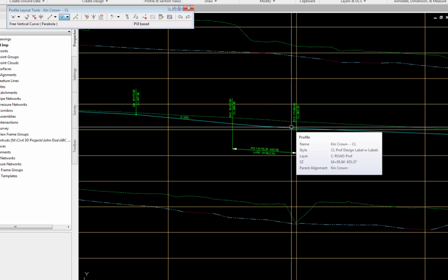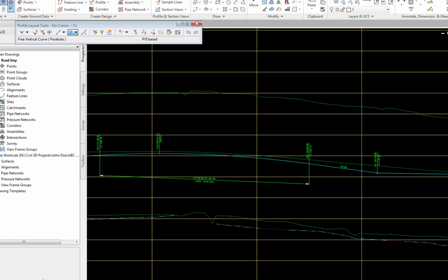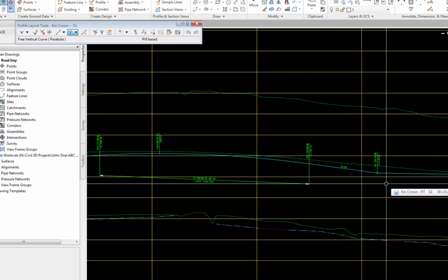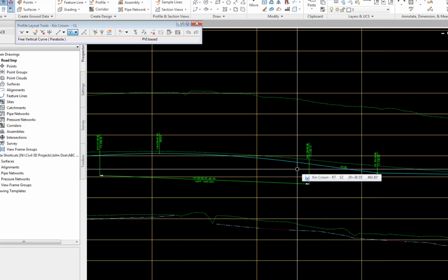Enter. It is desired for the length of the vertical curve for the PVI at 30 plus 15 to be 130 feet, with the BVC being at station 29 plus 50. This is also the EVC station of the 200-foot vertical curve for the PVI at 28 plus 50. Civil 3D will not allow the coexistence of this BVC and EVC.